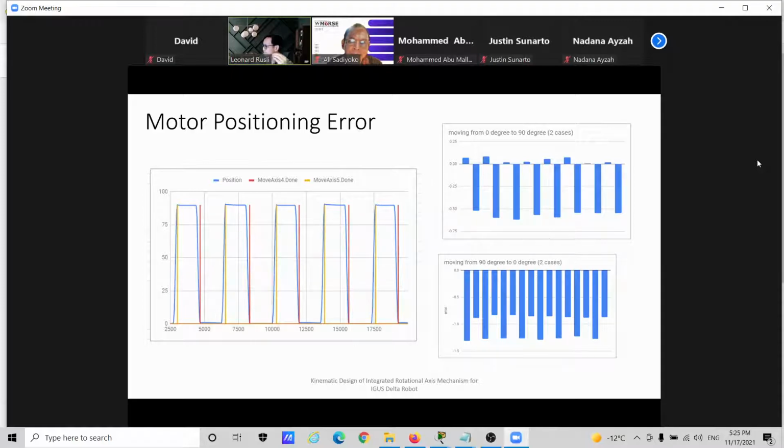Hold on, let me look it up again, just to make sure I got this right. It is 0.1 millimeter dimensional tolerance on the 3D printer. And therefore, this translates to about half a degree in the rotational axis. Now, we do have 3 points where this can introduce an inaccurate position and introduce a backlash to the kinematic linkage. One at the top U-joint, one at the telescoping member, and another one at the bottom universal joint.